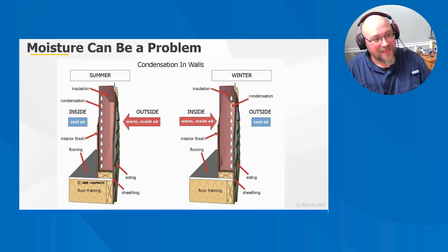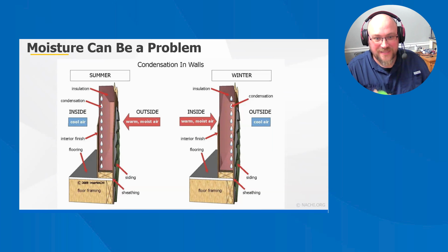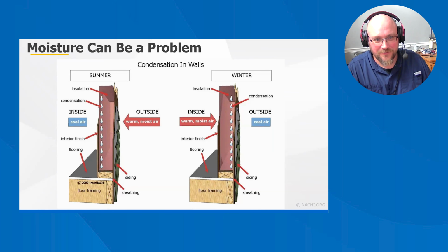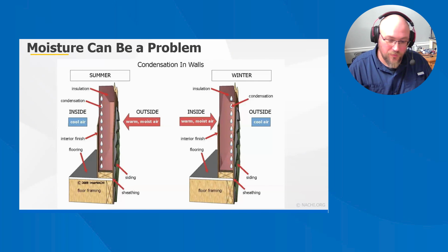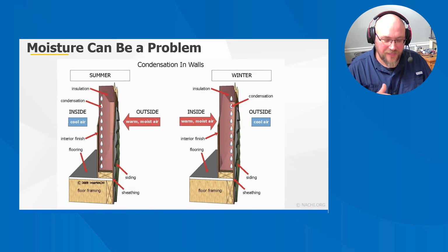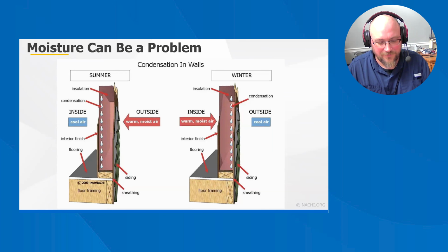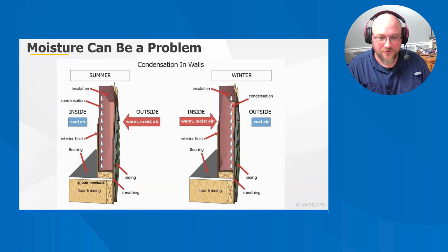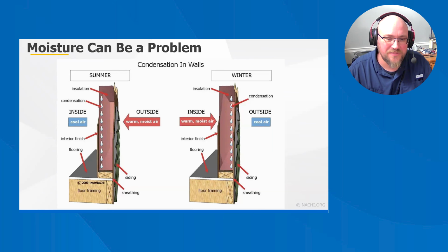that wall super cold. And they had really warm, moist air inside the home from all those people living in there, so it created a super cold surface. And in Arkansas, we don't use sill gaskets, or you're not required to use sill gaskets. So when that air was coming in through the weep holes, it was uninterrupted underneath the sill plate, and it was coming into contact with the floor trim or the baseboard. That surface was super cold, and you had the super moist air contacting it, and it was condensing and starting to create moisture damage issues along that baseboard.